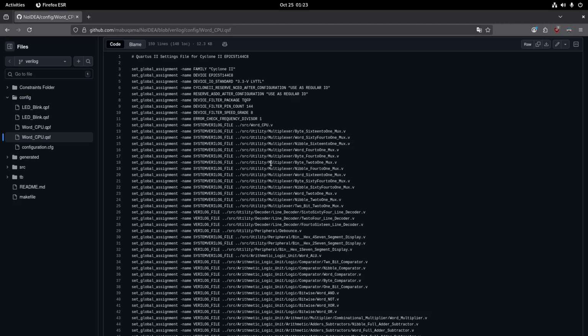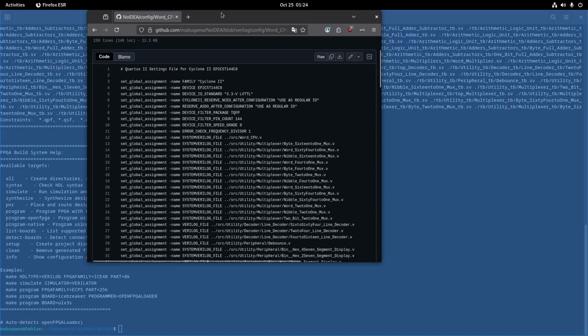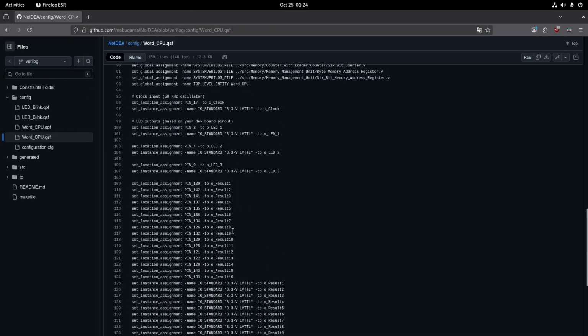It also says which HDL. The nice thing about my script is I can mix HDL languages. So I can use SystemVerilog for one file, Verilog for another, or VHDL if I really wanted to. But I've ended up using SystemVerilog and Verilog. The reason is that there are some ease-of-life features in SystemVerilog that are not in Verilog. They are basically both the same description language, kind of like how you have C and C++. C++ has a lot more features. It's a superset. Same thing in Verilog.